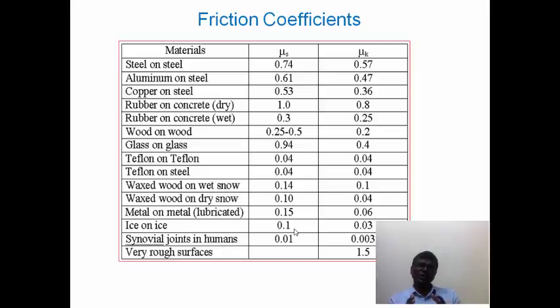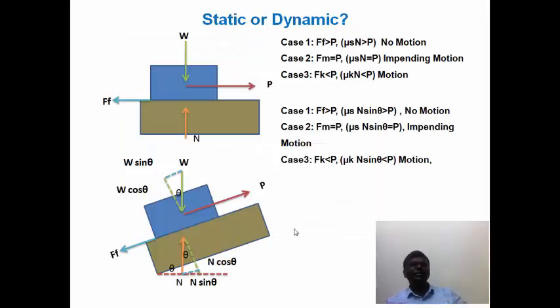So it is very important that when you make a design, we should take consideration of this friction coefficient of the interface material. So let us look into the two cases. One is the block on the plane. So applied force is P, and the load due to its own mass is W, and the friction force is acting against the applied force, and the counter force from the counter surface is the reaction force, basically you can say.